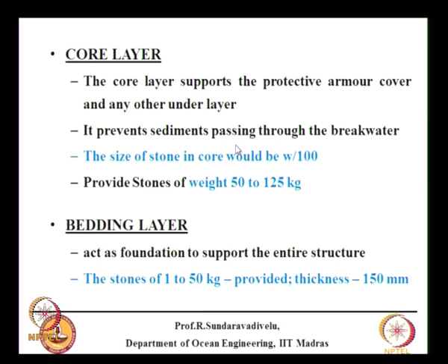So this is important. Whenever there is a sediment which is suspended in the water, that should not go through the breakwater. What happens if it goes through? It will go inside and settle and you have to dredge. It will go through the armour, because armour has a lot of voids. It may go through the underlayer, that also has voids, whereas the core layer you make it in such a way that the voids are minimum and it will not go through this.